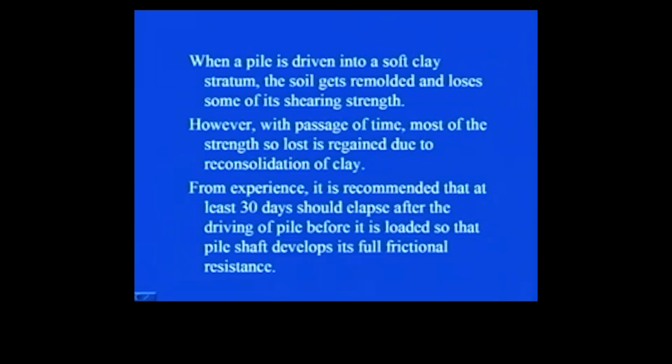So, you have to give some time so that the clay can regain its strength which it has lost during the process of driving. Okay. So, pile is getting driven, the soil is getting loosened and remolded. So, it is losing some of its shearing resistance. With passage of time it regains. So, you have to give at least 30 days time such that the soil can regain its strength and it can develop its full frictional resistance.